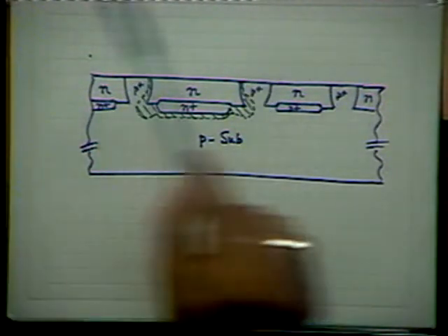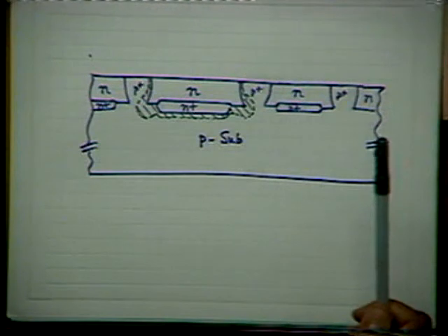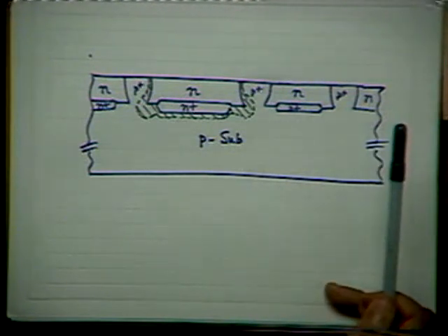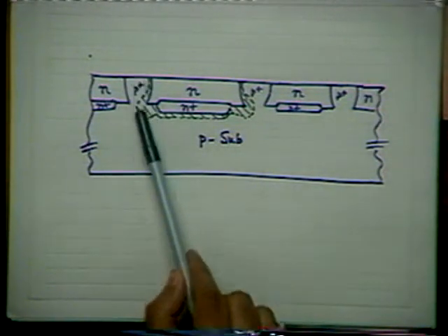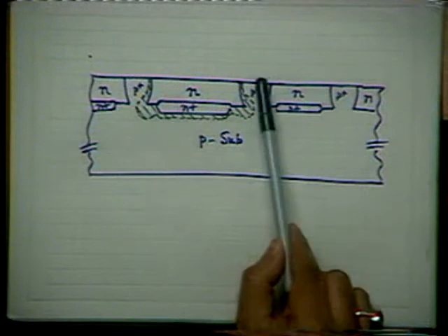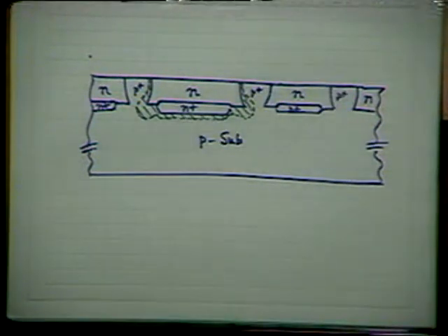You remember, by a photolithographic step on the N-type layer, I etched windows here, here, here, and then had a doping of boron, very heavy concentration, through these windows, so that ultimately we get a continuous p-type region here, here, here. All the N islands are surrounded by p. You remember the technique.